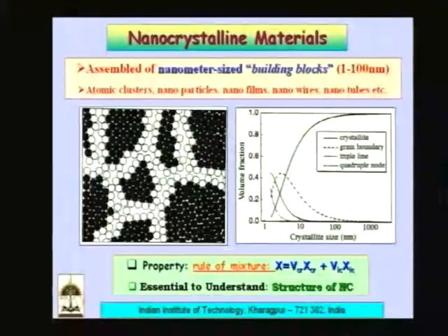And we usually know that the grain boundary is basically a disordered region when compared to the grain. As you can see here, the black regions are all the grains which are ordered arrangements of atoms, okay, and the grain boundaries are basically the disordered region. In fact, long back when Gleiter discovered these nanocrystals, he even said these grain boundaries are gas-like structures. Though people have proved a little later using high resolution microscopy that there is no such gas-like structure really in the grain boundaries, definitely there is some kind of a disorder there.